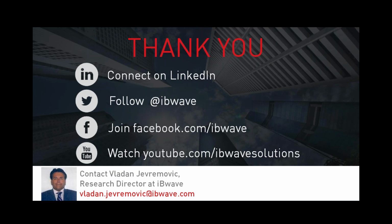We have actually mentioned in our white paper, we have a reference that basically says that 2 to 3 seconds is needed for each handover attempt, but you cannot leave just that one attempt as an option. You have to let the UE try 2 or 3 times before you declare that handoff attempt unsuccessful. So let's say if it is 3 handoff attempts, and then it is 3 seconds for each attempt, then 9 to 10 seconds should be budgeted for the UE to complete the handoff.